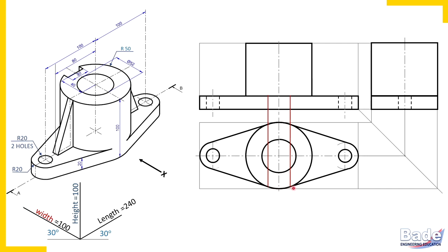I have drawn these projectors, these two red color projectors. Check here. This portion I have erased because it is a tangential joint here. And these two edges, watch here, this non-principal edge and this non-principal edge meet the curved surface tangentially. So we'll use the proper notation to indicate the tangential joint. So this is how we have created this joint.